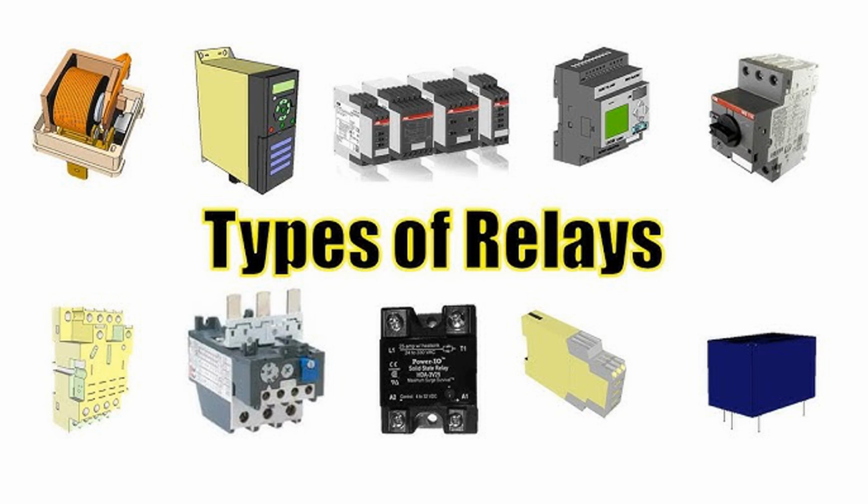Key characteristics. High sensitivity. Differential relays are highly sensitive to internal faults and can detect even minor differences in current. Zone protection. The relay is designed to protect a specific zone, such as a transformer, generator, or section of a bus bar. Fast operation. These relays have a quick response time, crucial for protecting high-value equipment from rapid internal fault escalation.